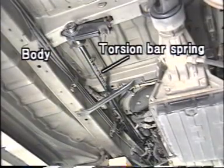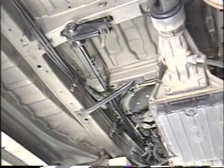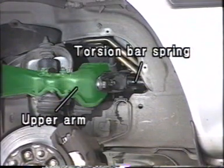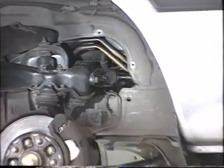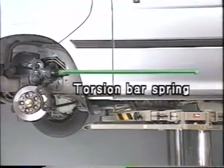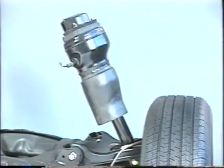One end of the torsion bar is anchored to the frame or to another structural part of the body, and the other end to the suspension arm. Torsion bar springs have a simple construction and are compact. For this reason, torsion bar springs are often used in one-box type vehicles.